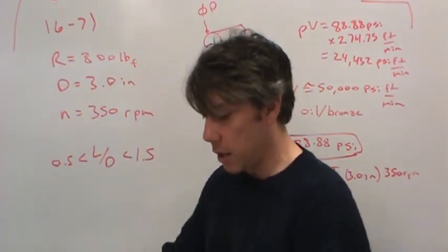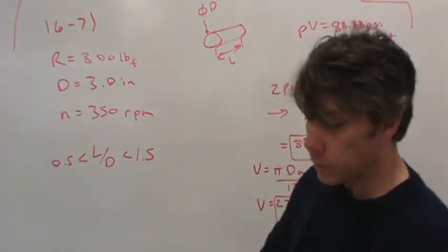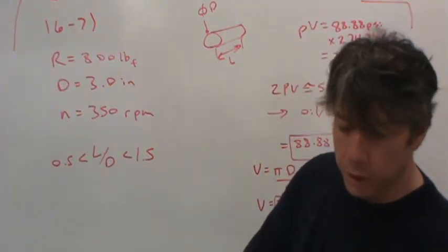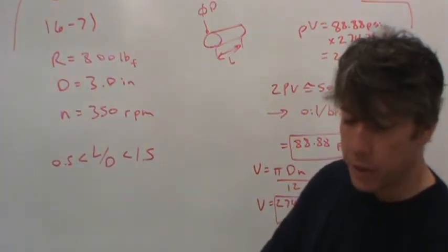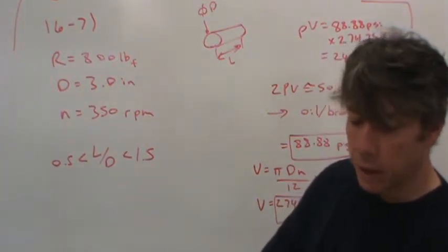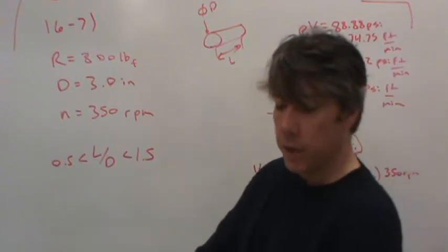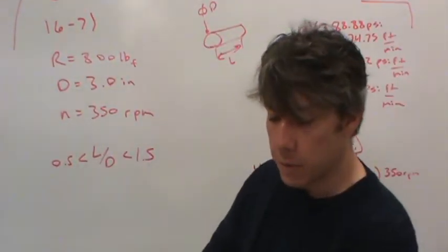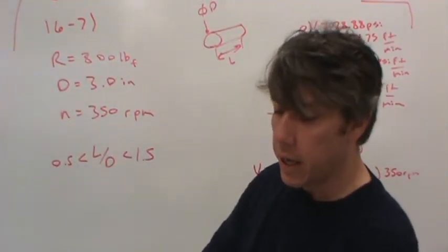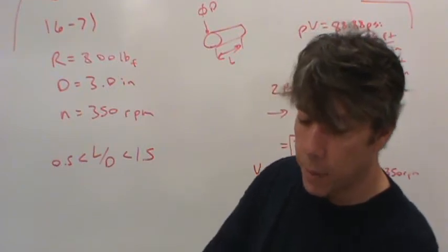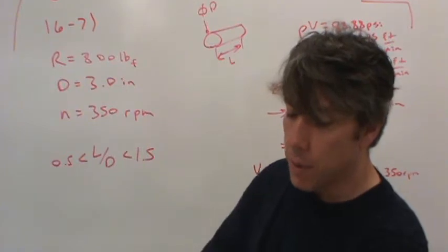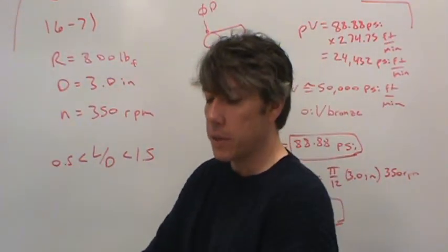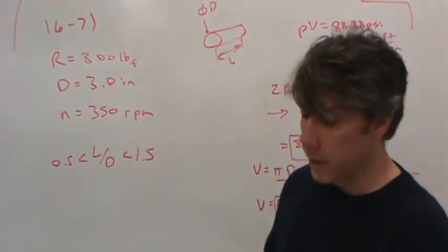Figure 16.4 shows recommended minimum values for clearance based on journal diameter and rotational speed under steady loads. These values apply to the smallest clearance under any combination of tolerances on the dimensions of the bearing system to avoid problems of bearing heating and eventual seizure. The operating clearance will then be higher than these values because of manufacturing tolerances. Performance over the entire range of clearances should be evaluated, preferably by testing.